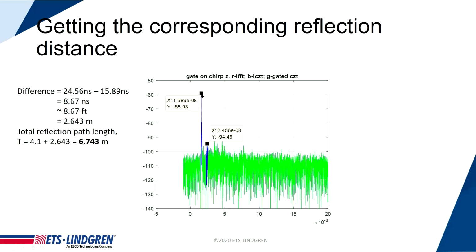Then we can see that in this chamber, we definitely have quite a few reflection points. We don't really know which one is going to make this chamber fail. Of course, in the post-processing, this is fairly easy to do. We can say, let's try one at a time. We can look at this one as a reflection and manually delete this reflection mathematically. At this point, it's all post-processing. We don't even need to go back in the chamber to do this. We delete this reflection mathematically, then transform back to see what the VSWR would look like. You go through the same process and get the VSWR.